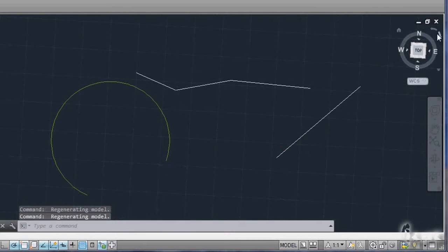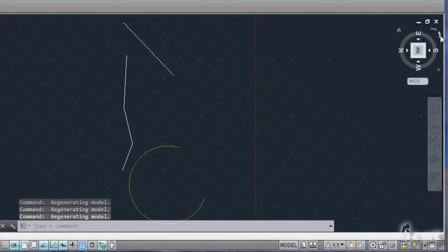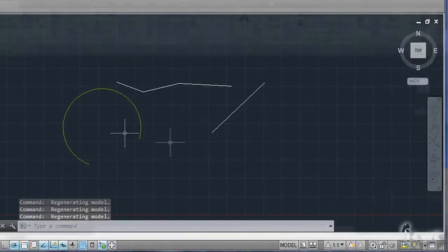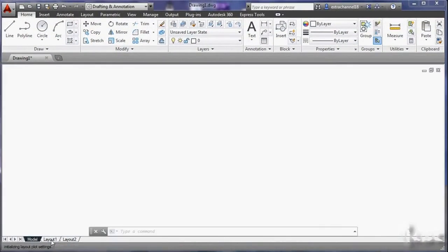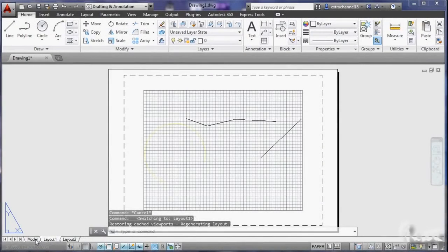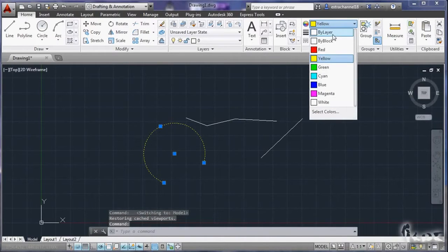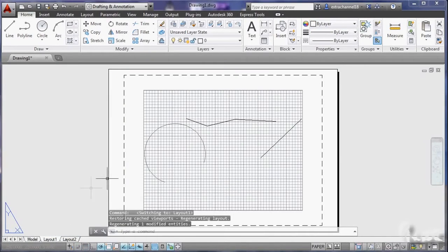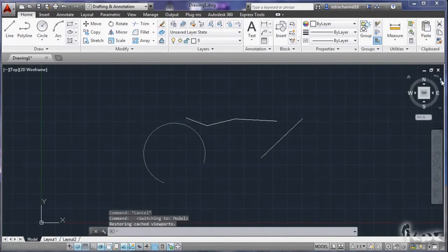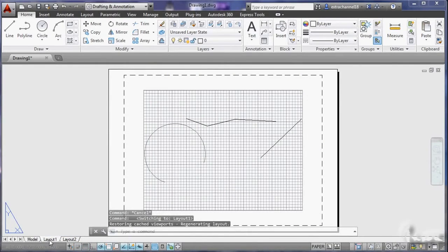You can use also the hidden arrows in the top right corner. This does not rotate objects, but just your point of view or camera. At the bottom you see some options, like Model and Layout 1 and Layout 2. The model is where you are going to work. The layouts are the preview of your drawings. In short, what you would see if the page was printed. Rotating the workspace using the 3D map won't rotate the drawings in the final layout, since they are used just to change the point of view.